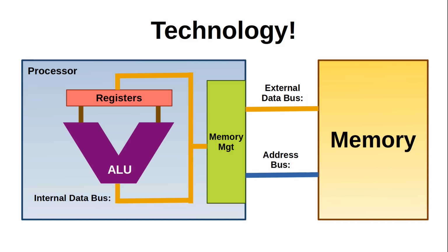And within this architecture, you're going to be dealing with memory data and bringing that into the processor. And that data is going to be digital data. It's going to be ones and zeros. And however many ones and zeros are in that word that you pull out of memory, that's going to be the bit width of the external data bus.